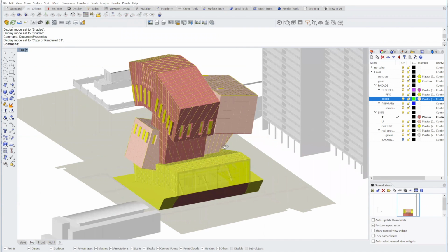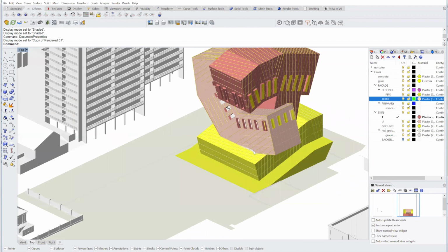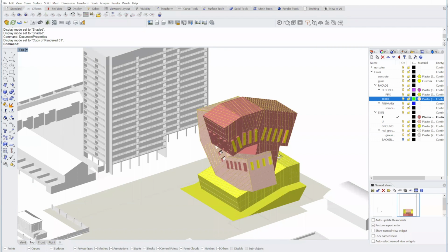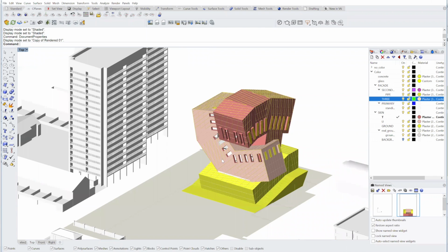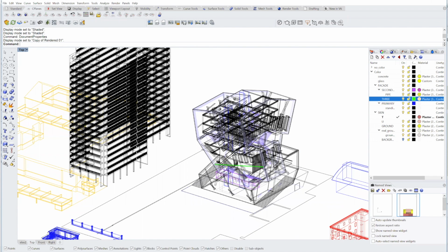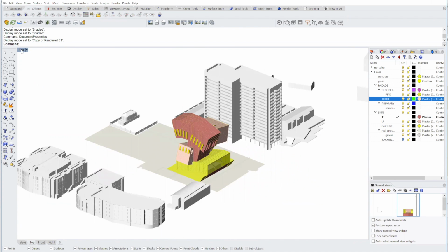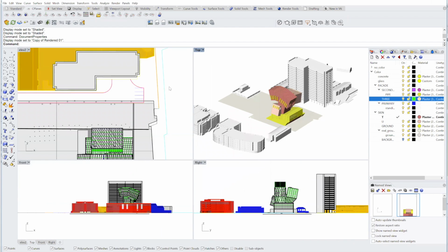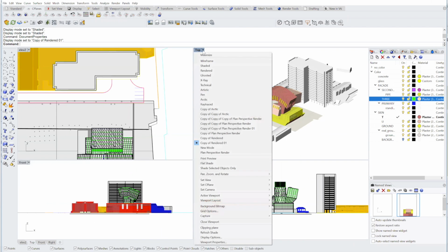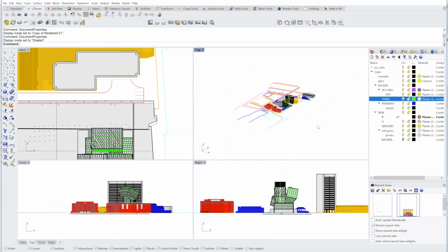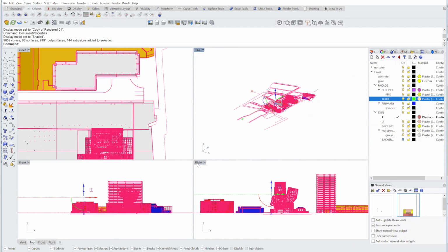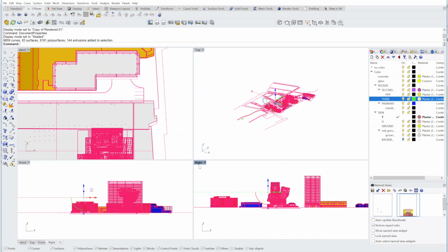So rather than actually render this in V-Ray or in Rhino Render, I'm going to use a high-resolution screenshot to render this. The thing that's nice about the high-resolution screenshot is that you can get an image that has a lot of pixels, say 20,000 by 20,000, and it takes only a couple of seconds. You can also get a lot of different views quickly if you just set up the colors on your model. So as you see here, I've switched back to shaded mode. I'm going to show you how to change this into a plan or into an oblique drawing.